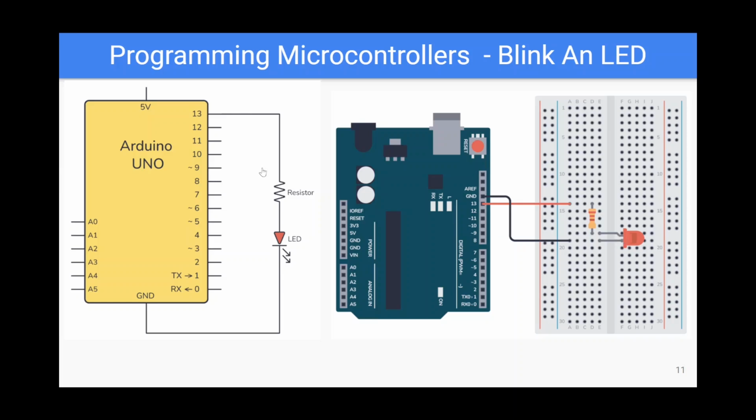Okay, so what we are doing here: pin 13, the wire comes to this breadboard, and there is a separate video available on the portal where you can understand what the breadboard is. When we connect here, all these holes are connected together, so that's why it's connected with this resistor, and this resistor is connected with the anode side of the LED, and the other side is going to ground, as you can see here. That basically completes the connections using the Arduino Uno.